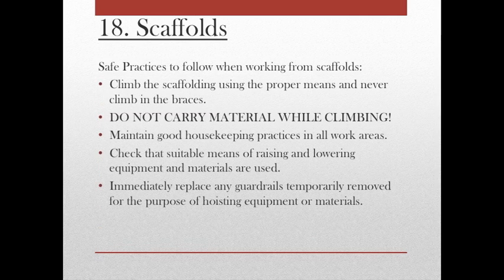Immediately report any visible defects in the scaffolding to the project superintendent. Safe practices to follow when working from scaffolding: Climb the scaffolding using the proper means and never climb on the braces. Do not carry materials while climbing.